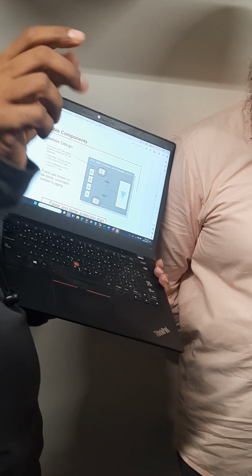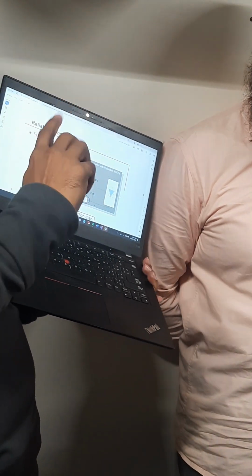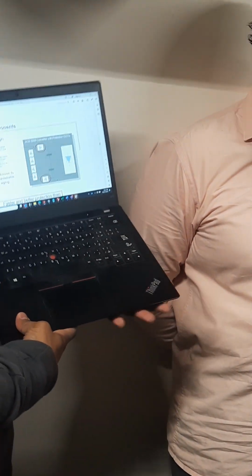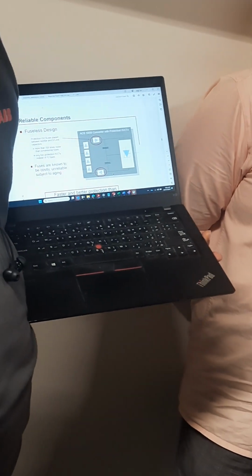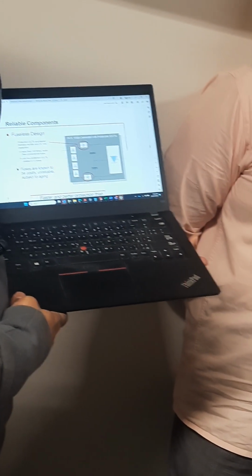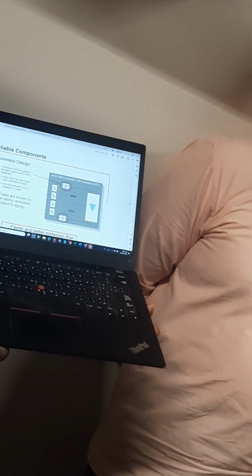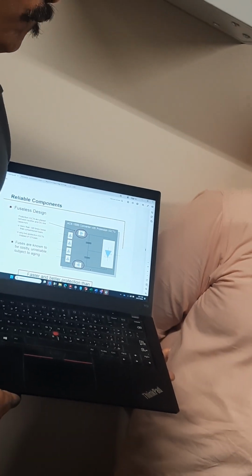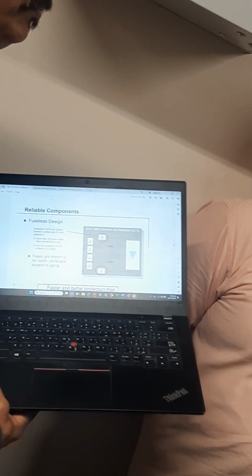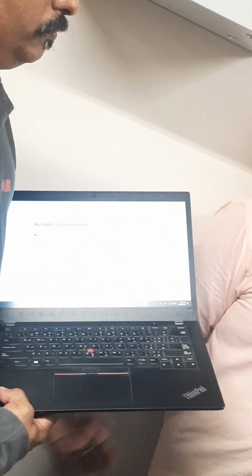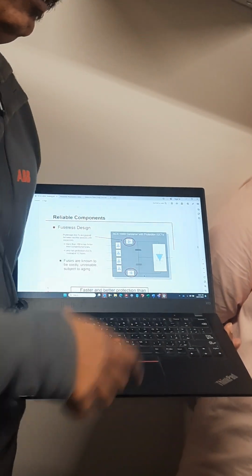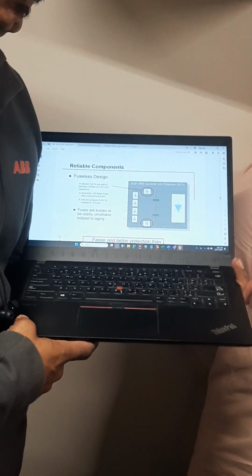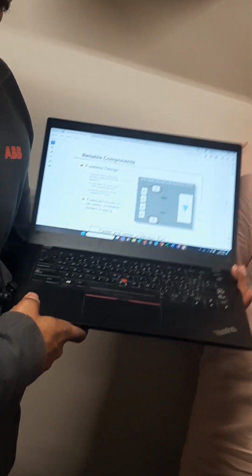That circuit should not be tripped in any case, because if it is tripped you will get a control supply loss code. That supply is through the UPS. For the chiller control circuit and the VFD control we have a UPS. For the chiller three-phase supply, there is no UPS, so you have to check that. I will check directly from the breaker. Okay, everything is okay, water is there, everything.